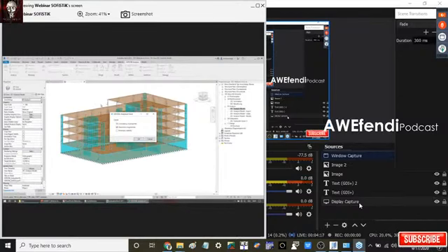This check has been enhanced with version 2021. So we now distinguish between different classes of checks. A first check checks the properties of the elements, so whether materials, for example, are appropriate for analysis. We are also checking the geometry. So, for example, it could be that two surfaces overlap, and these kinds of issues are reported when activating this check.